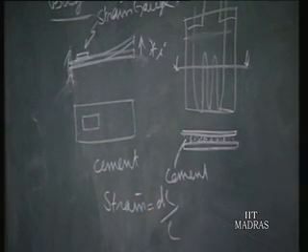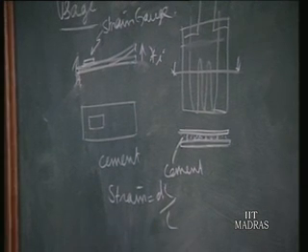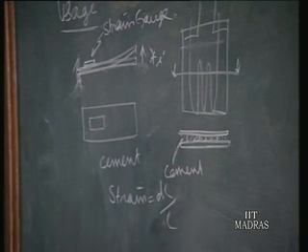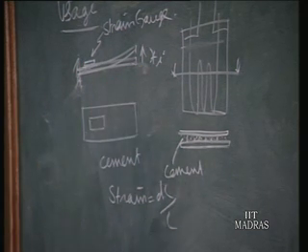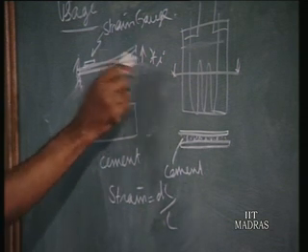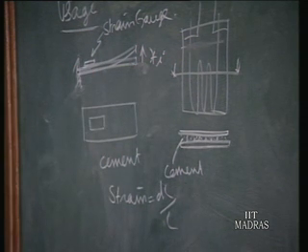When there is strain, you have the gauge factor multiplied with the strain, giving the resistance change in the strain gauge. This is what is happening. So you give the motion to the end of the cantilever, and the motion is measured by using the strain gauge. In this process, we should know the direction of the strain.